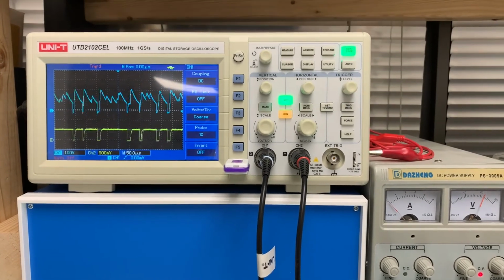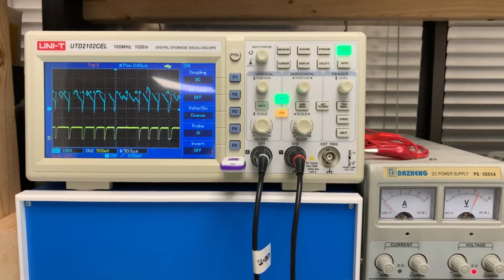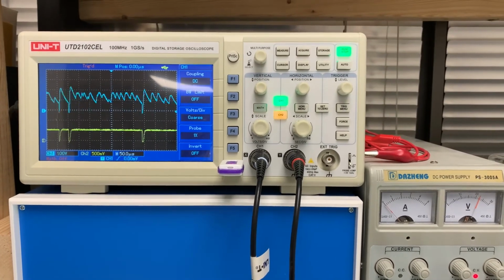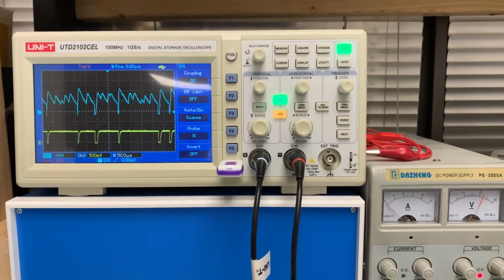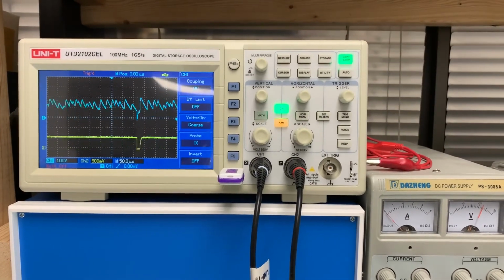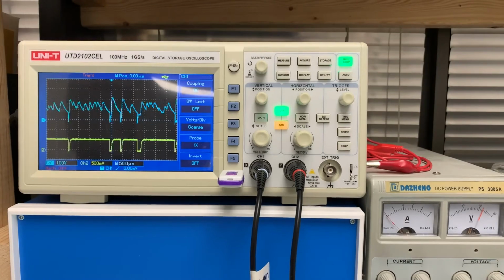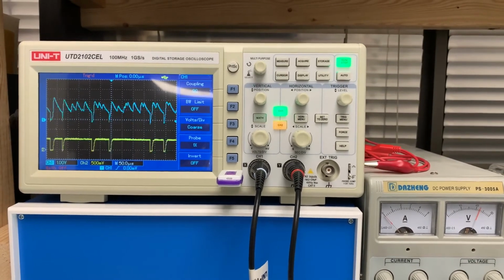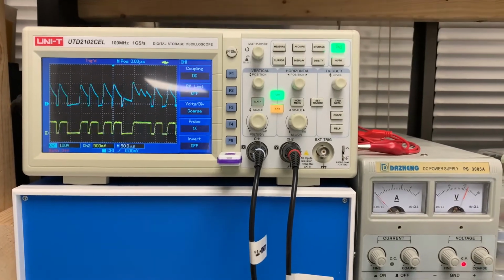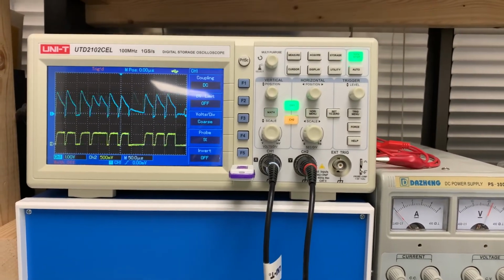There's almost no, I would say there's no downtime. It's just straight flat at 5 volts almost in terms of the comparator output. So it's getting triggered like crazy, but I think that's not a good sign because then we cannot really count. So let's not put the light that close.